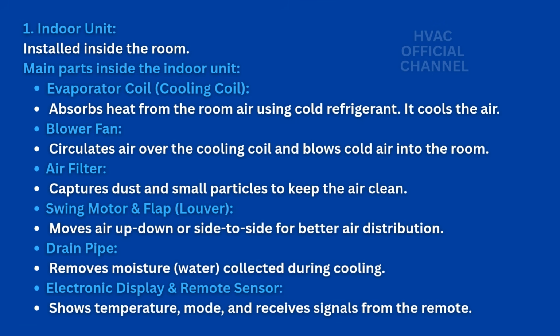Main parts inside the indoor unit. Evaporator coil, cooling coil: absorbs heat from the room air using cold refrigerant. It cools the air. Blower fan: circulates air over the cooling coil and blows cold air into the room.